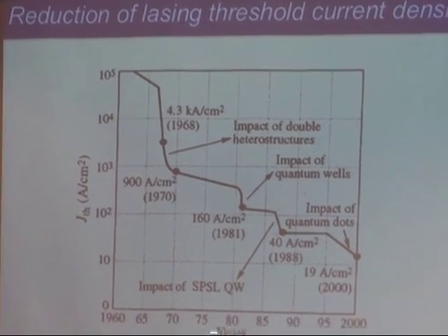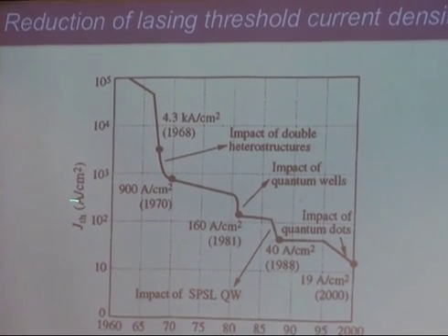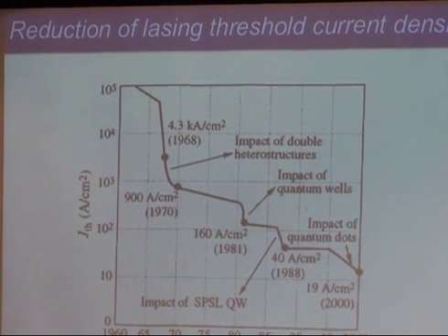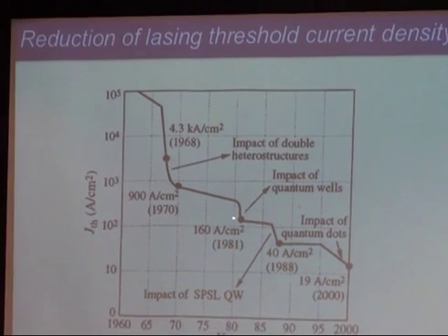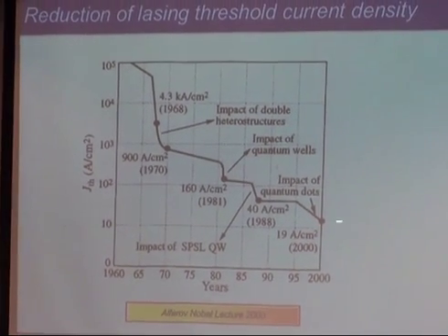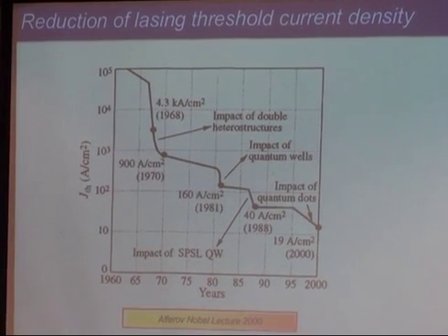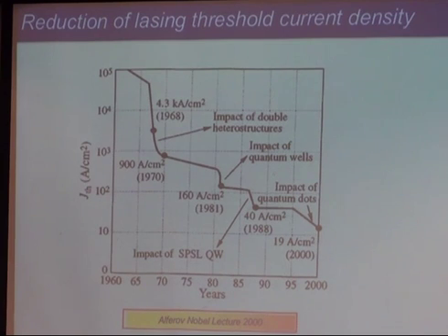So here's again alpha rho. By the way, this is also from an article that's posted on the web. Threshold current of lasers has improved over the last years since 2000, but you can see that it used to be bulk material and then double heterostructure with thick quantum wells, then very thin quantum wells with separate confinement and all this. This is a short period superlattice, SPSL. All these heterostructure designs went from 10 to the 5 to 10 to the 3 to 10 to the 2. With quantum dots, you are talking about 10 amps per centimeter squared. It's very, very low threshold now. The ultra low threshold lasers, this is for infrared long wavelength lasers. So 10 amps per centimeter squared is kind of in the LED region. This is extremely low threshold and very high efficiency now. So that's a nice improvement.